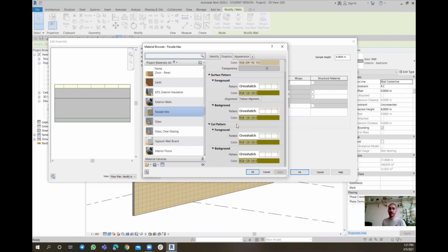Most of the cases, it's pretty easy. For example, if you have gypsum, or masonry blocks, you go there, you replace this material, and that's it. No need to do all these modifications. But here, the case was that the travertine stone that we assigned wasn't having, let's say, the tiles naturally on it. So since we didn't have the tiles, we were supposed to create customized tiles. For that reason, it got a bit complicated. But in most cases, the material itself is actually good to go.